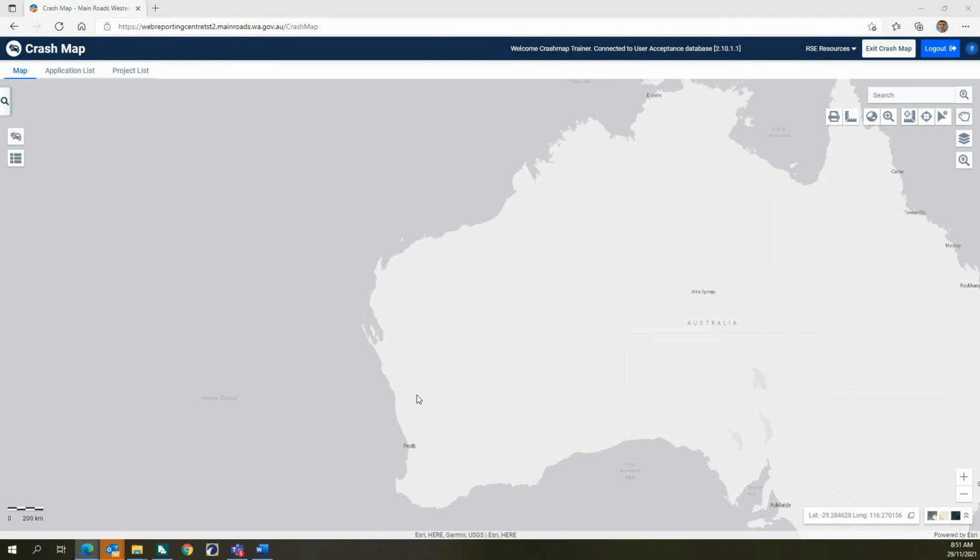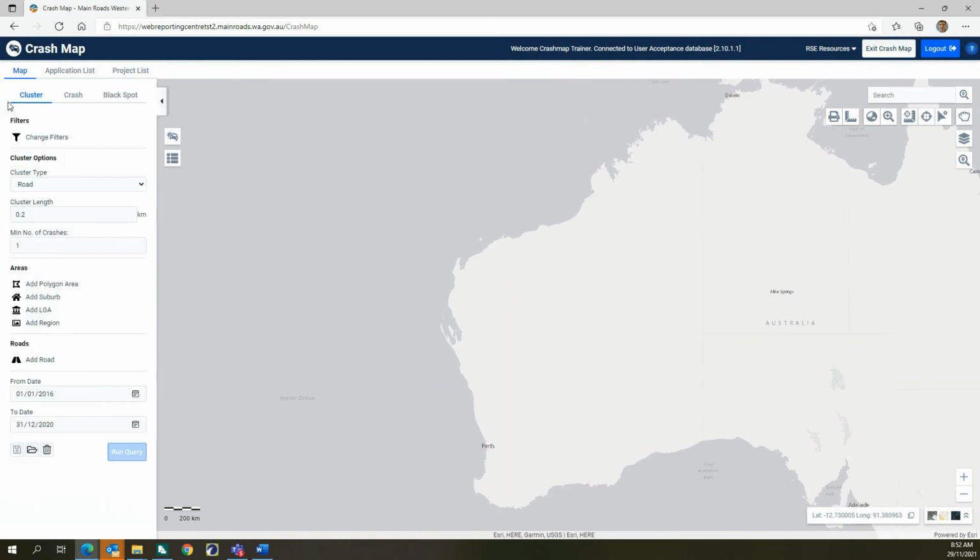The risk scores also give priority to locations with higher road user exposure, such as higher vehicle volumes and other road user volumes. You should also ensure that the findings identified in your road safety inspection report clearly identify the crash risk in each finding. This is because the crash risks stated in the road safety inspection findings are used to validate the crash risks that are addressed by the treatment selected. If you focus on these factors, your inspection-based blackspot will achieve a higher score and you will be more likely